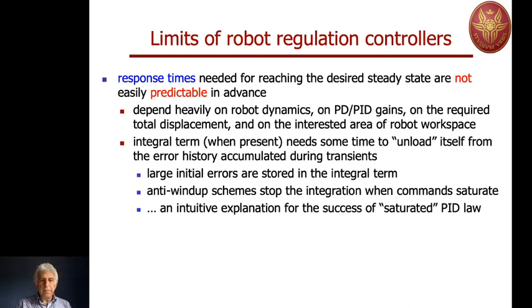There's another aspect when we are dealing with the integral term, when it's present. This tends to make the final response time longer, because in the integral term we load all the errors of the trends. So even if the robot is starting from the beginning and going in the direction of the desired configuration, so everything is working fine, still we accumulate error.